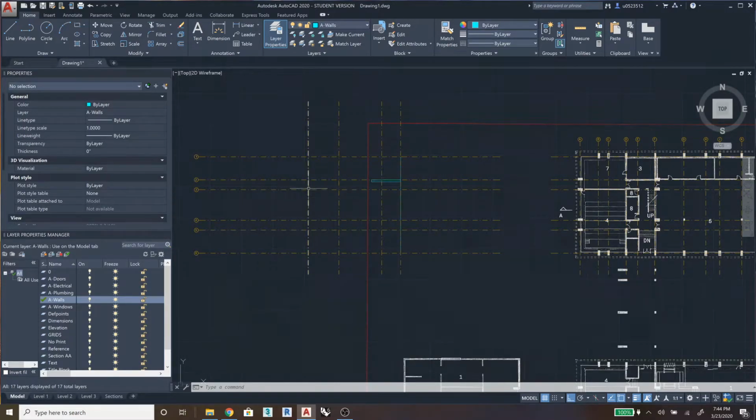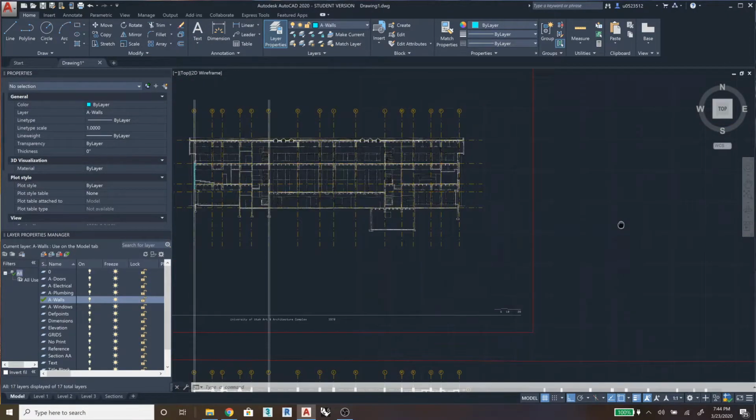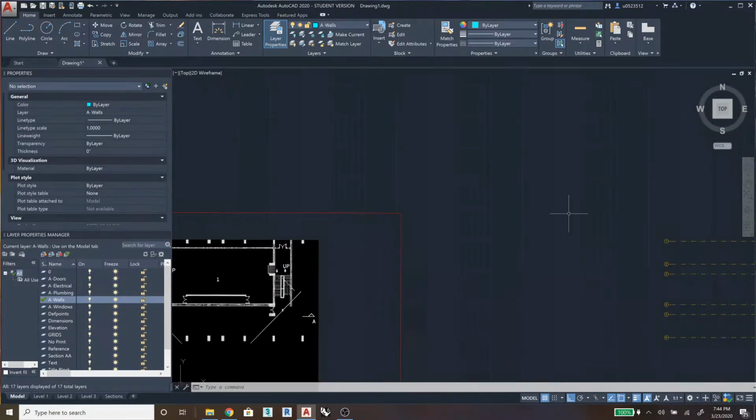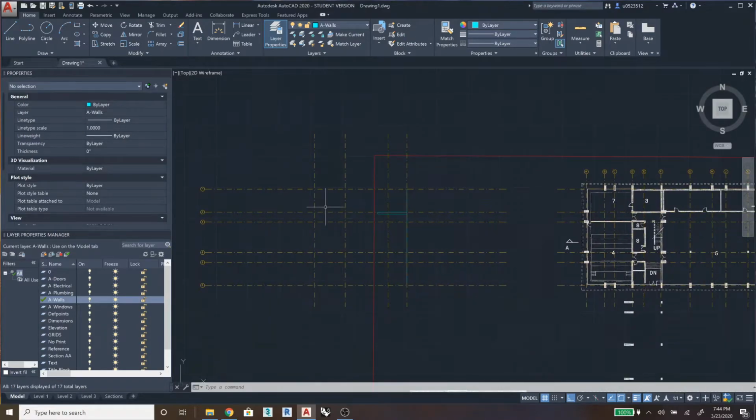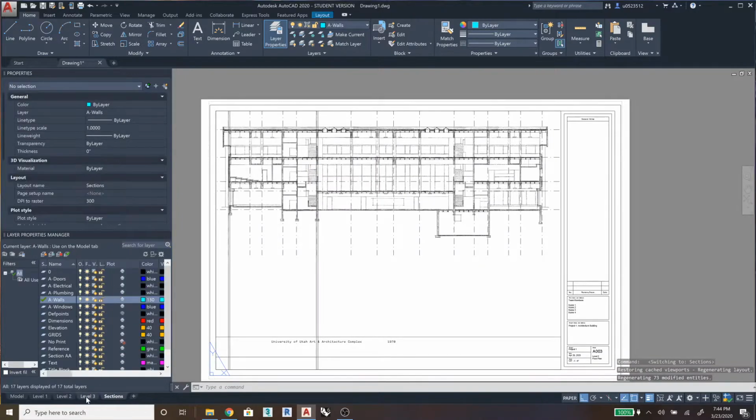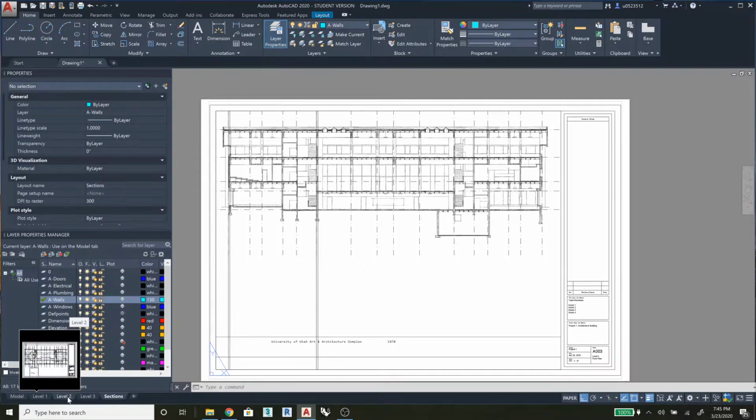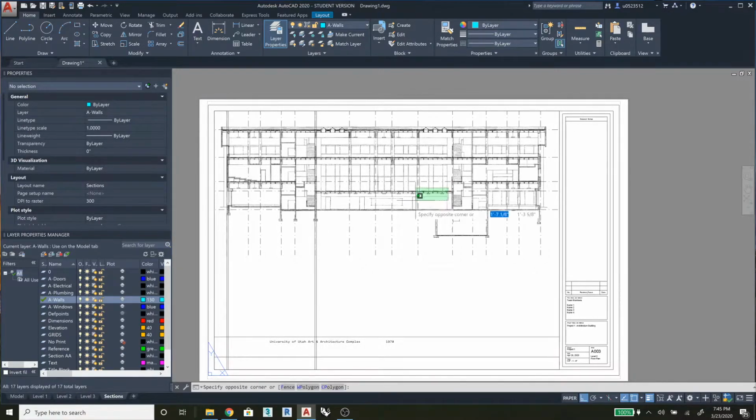And then you can also view your other section at the same time without having to pan all the way over here every time you want to get some information from the other section. So I'm going to show you how to set up that layout. I've just copied over level 3. I copied it over here by pushing Control and dragging it. You can also copy level 2 and drag it in between these two and then move it, rename it, however that works. Now I've kept this section.